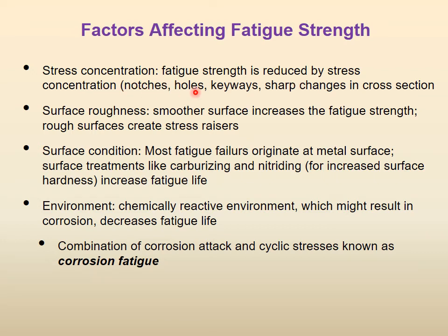So notches, holes, keyways, sharp changes in cross section, if they are there in the material, then of course a stress concentration will be there, and that means the fatigue strength of the material will be lowered.